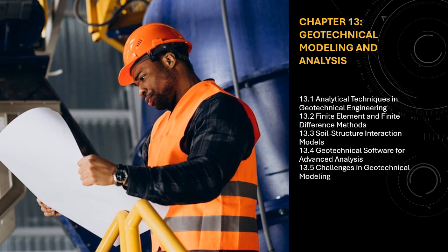13.4.3 Choosing the right geotechnical software. Selecting the appropriate software depends on several factors, including complexity of the problem. Simple problems such as static loading of a shallow foundation may be solved with simpler software, while more complex problems, e.g., large-scale dynamic analysis or 3D soil structure interaction, require more advanced tools like FLAC or Abaqus.